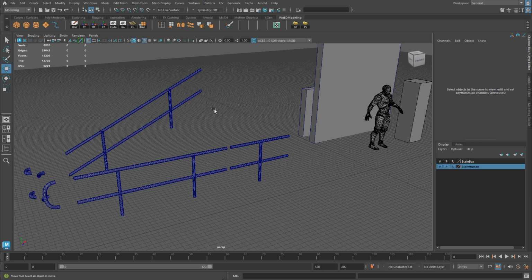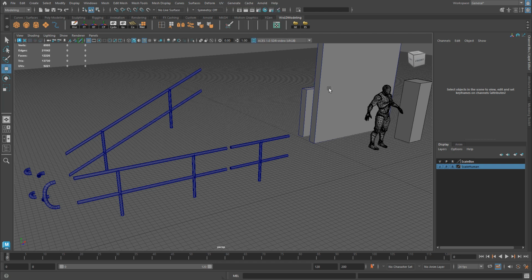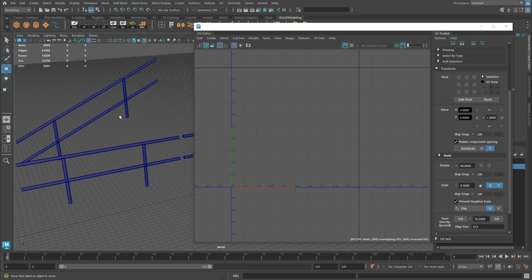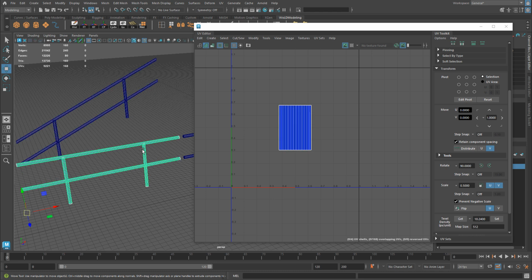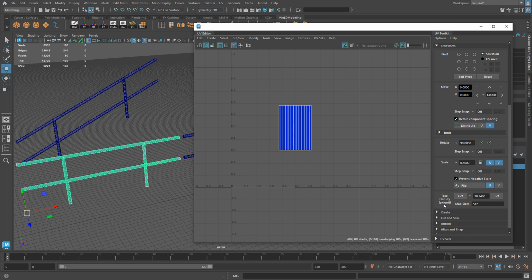So I want the UVs for these railings to occupy a certain amount of space inside the UV layout, inside the 0 to 1 space, so they look good and the texture resolution is correct and it's to the proper scale inside UE5. So to figure this out, I am going to use a 1K texture, 1024 by 1024, for 1 meter of geometry. And then once I know that value, that texel density, I'll be able to resize these UV shells for all the railings to match to that point of reference. And the texel density value is going to be found right here on the transform, and it's going to be used right here, texel density pixels units.